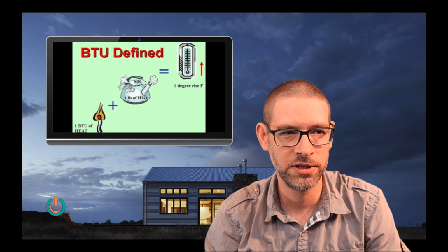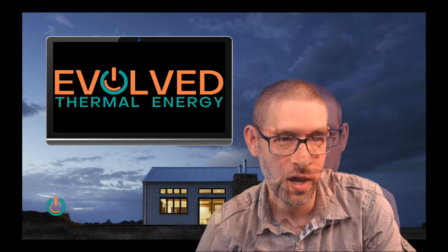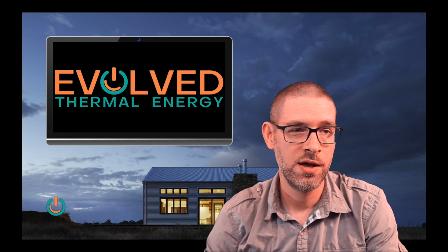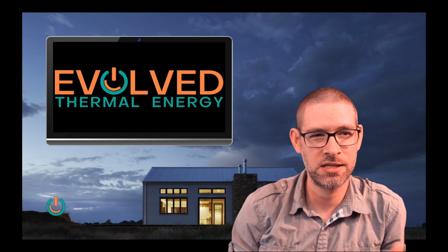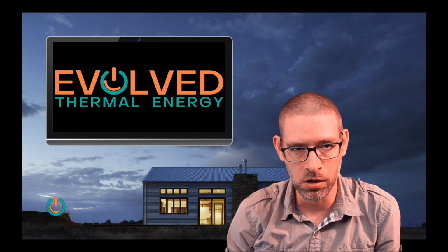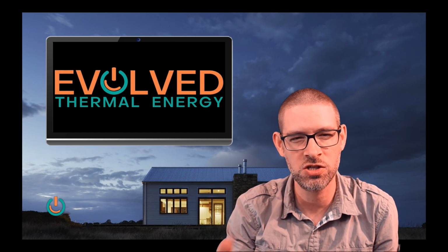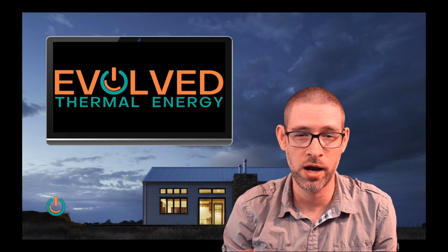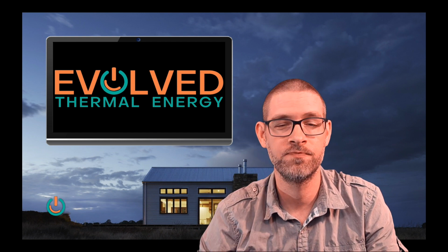And again, more commonly in Canada, in the metric system, we can convert that to kilowatt hours. 1 kilowatt hour is essentially 3,412 BTUs. Now, a kilowatt hour doesn't mean kilowatts you're using per hour. It is simply a unit of measurement that equals the amount of energy you would use if you kept a 1,000 watt or a 1 kilowatt appliance running for an hour. So it's the amount of energy that you would use.